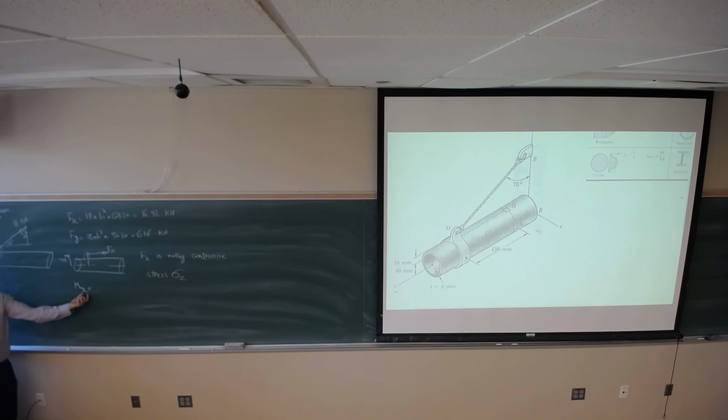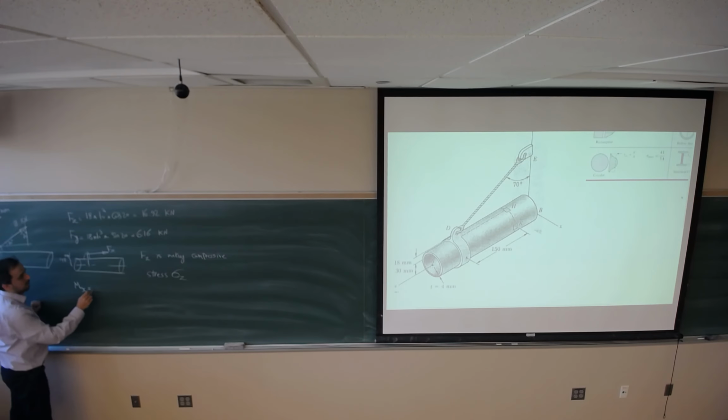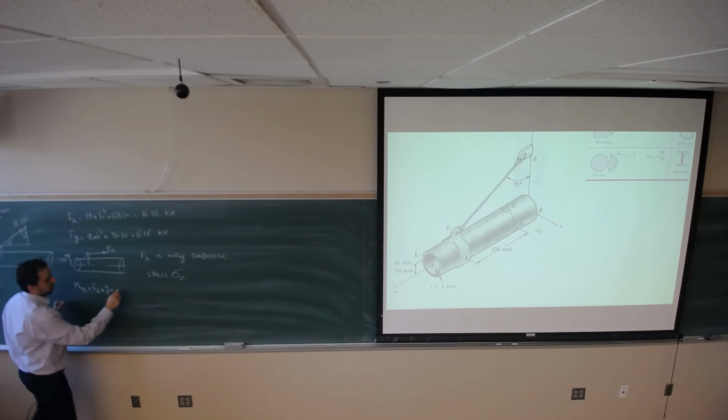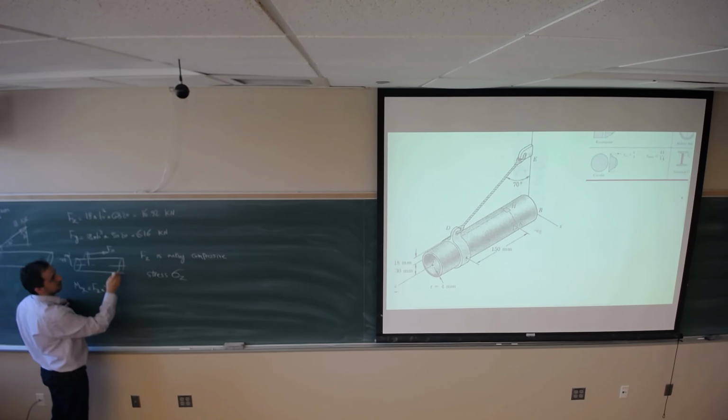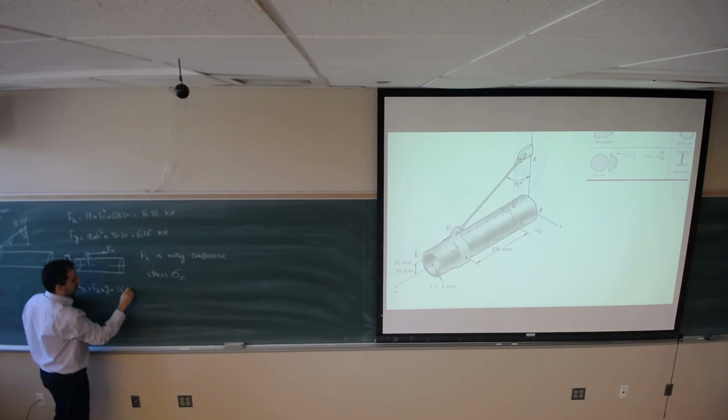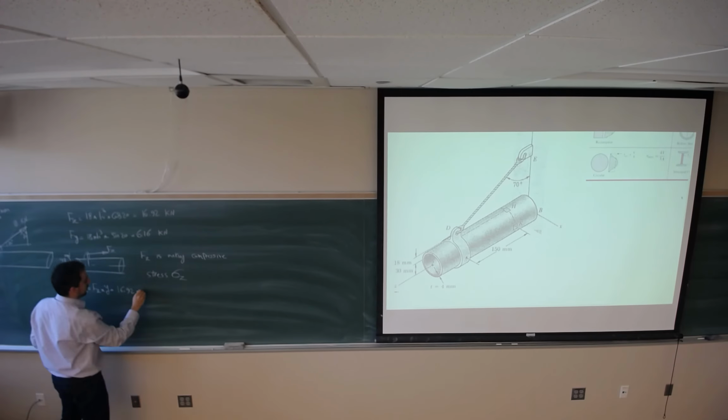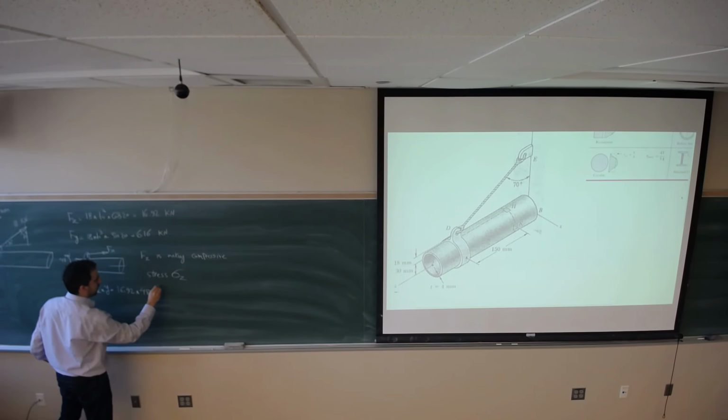This is important because it's going to tell you whether it is going to be the bending moment or the torsion. So this is how I need to find the direction of the moment. Fz times the y direction, which is 48 from the center of the pipe. So Mx is Fz times 48 times 10 power negative 3.